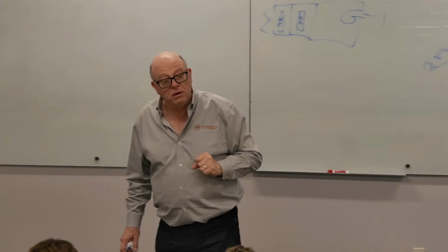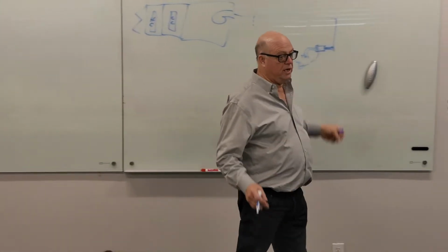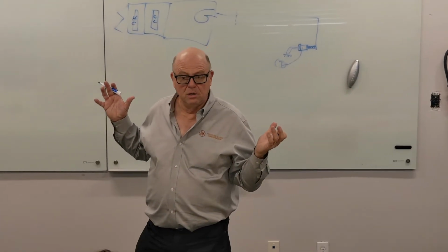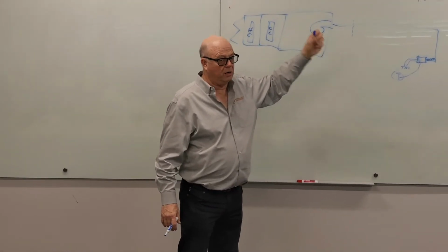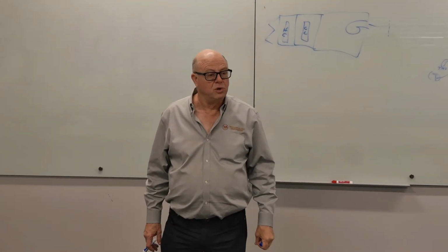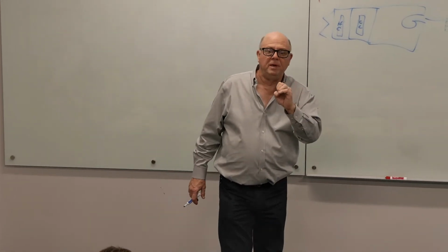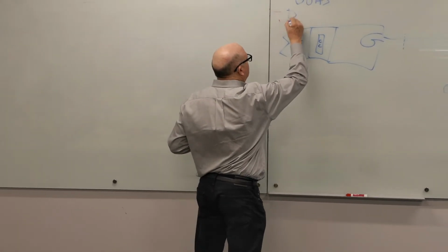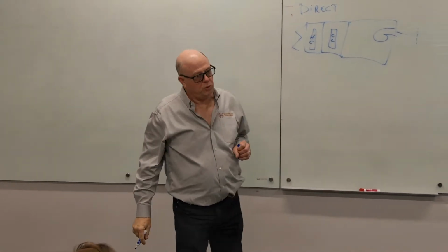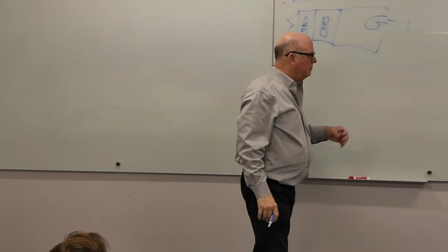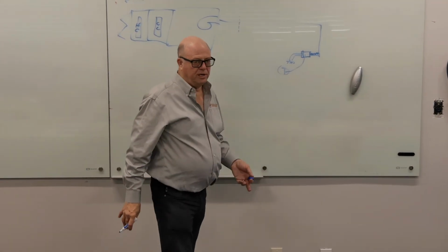We could do that. We could do that. Virtually every VAV box today has got an airflow sensor that's kind of sort of accurate. And it's not unusual for the air handler to have one too. So if we wanted to go to the effort of doing that, we could. And that would be a direct way to control that fan. But we don't do that. Cost is one reason. It's also kind of clunky.